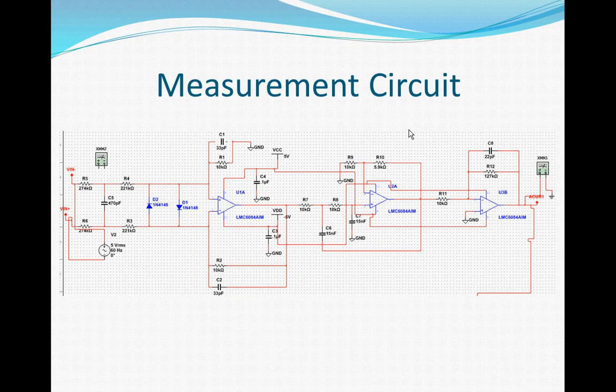The purpose of this circuit is to take that high 0 to 10 volts AC and essentially minimize it into something that's usable in a digital logic circuit that we could sample over and over, find the RMS value of, and voila, we have our high transmission voltage into something that's easily readable and scaled down to at the computer.